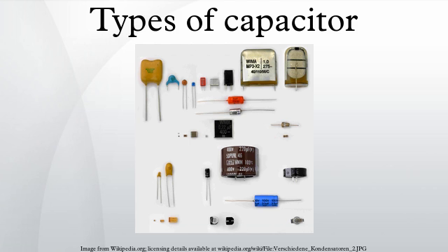Energy density. The capacitance value depends on the dielectric material, the surface of the electrodes and the distance separating the electrodes, and is given by the formula of a plate capacitor. The separation of the electrodes and the voltage proof of the dielectric material defines the breakdown voltage of the capacitor. The breakdown voltage is proportional to the thickness of the dielectric.